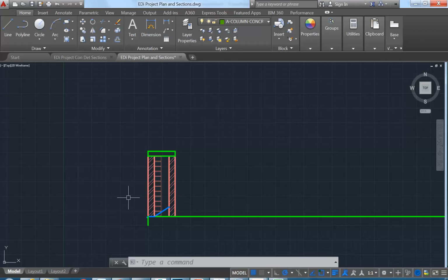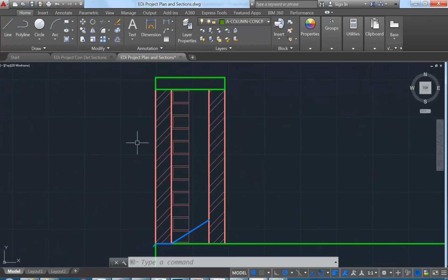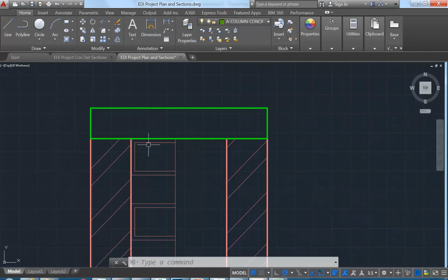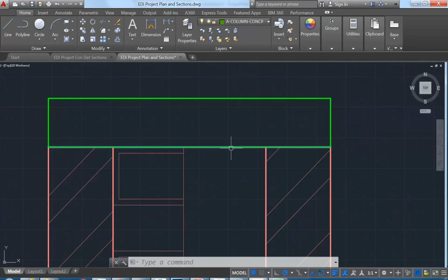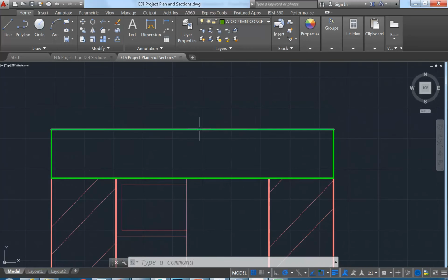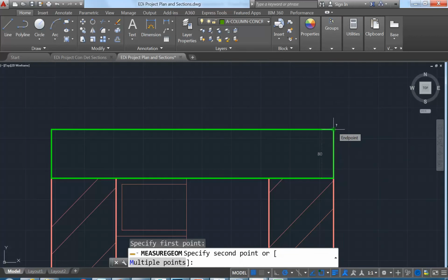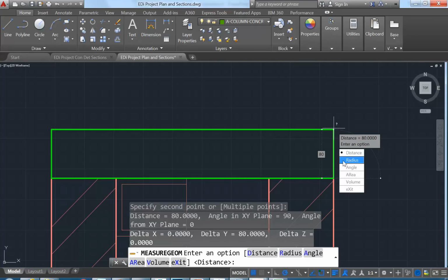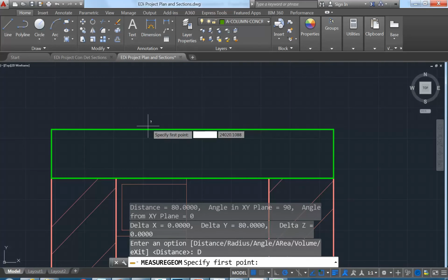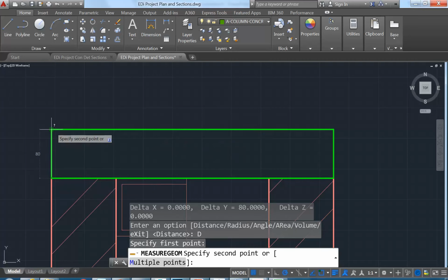Okay, so we've got the section there showing the brickwork under the windowsill, and if you haven't added this, well, I was going to say plinth, it's windowsill, then you could do it as I have with a fairly nominal thickness. 80mm is what I've worked it out to be, and I've just drawn it rectangular. We can always slope that.